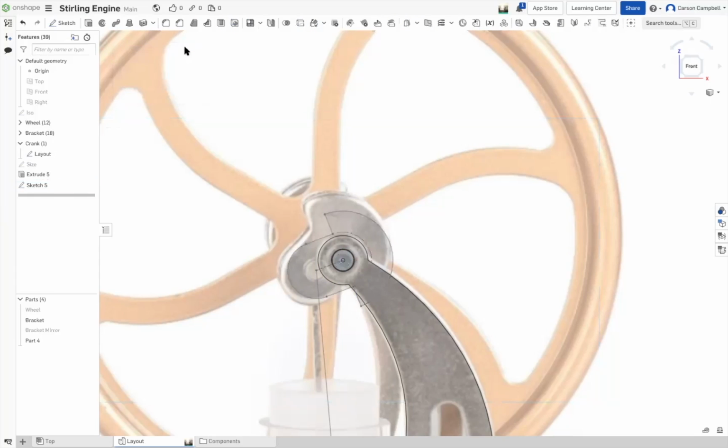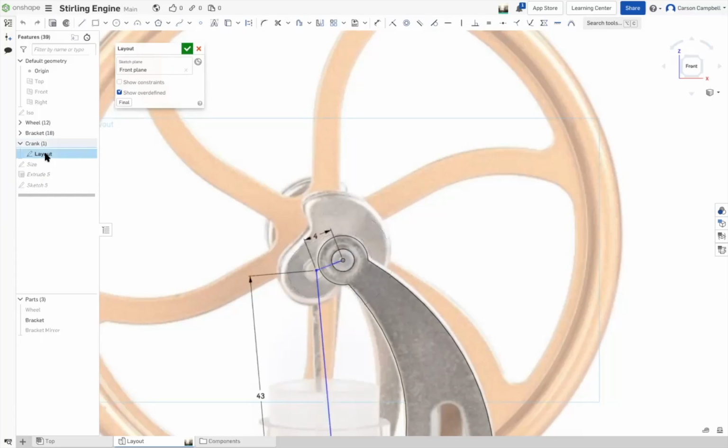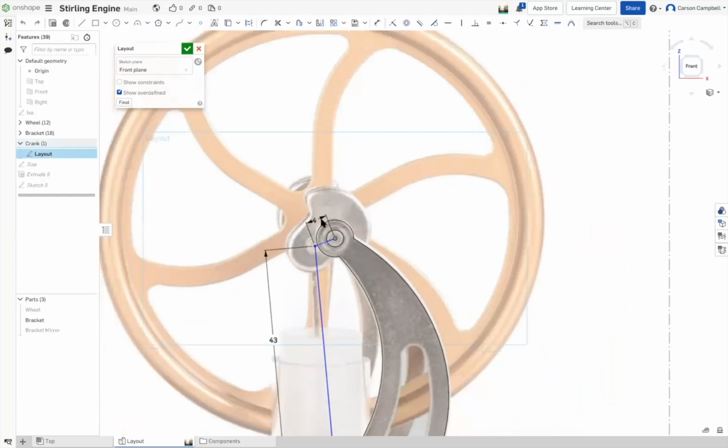And so this thing doesn't blow apart, go into layout, double click layout, and move the small arm just a little bit. That's good, because if it's not right, it's going to blow apart and go to Timbuktu. Click on the word final up there in your sketch.